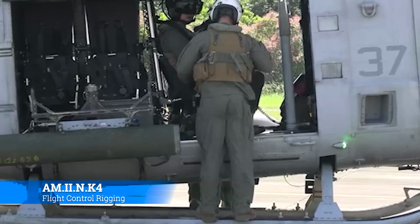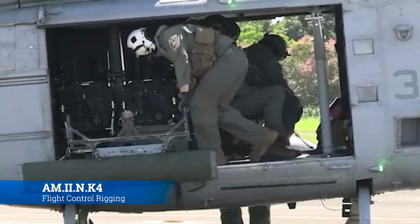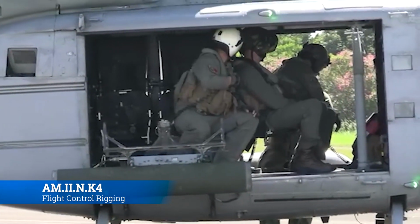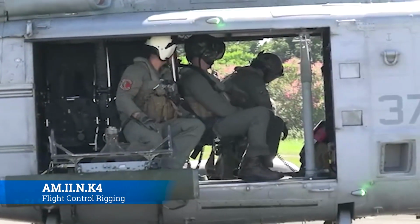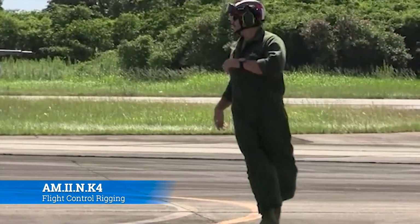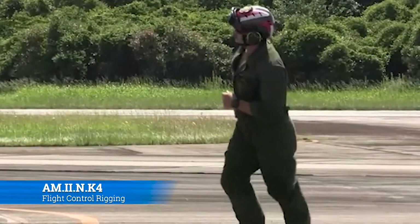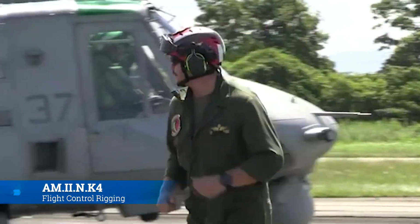You just make those adjustments, and then once both of them are in a static position, we'll call it, you're going to make certain movements. You're going to move the cyclic to a certain place and make sure that the blades follow, and then make adjustments as needed, and then go back to neutral. And whenever you go back to neutral, they should return to neutral.